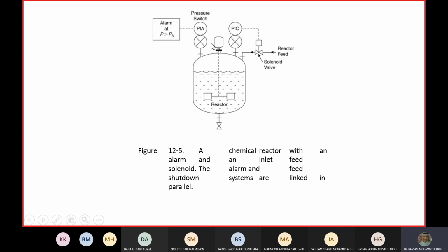Here the switch, the one with the X, is the switch. It will switch on this alarm if we have an overpressure, or in this case, it will switch on the controller if we have an overpressure. So these are the 2 things. Usually, a controller doesn't have a switch, as it's already connected directly. But if you have a switch, that means it takes an action like a shutdown system, taking action to that further system at a higher layer. So this is the system that we have.